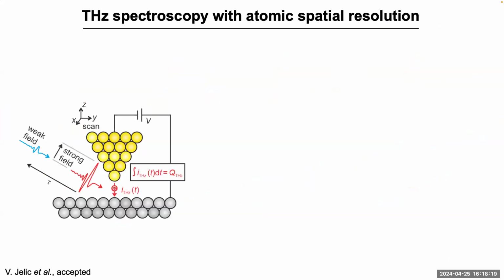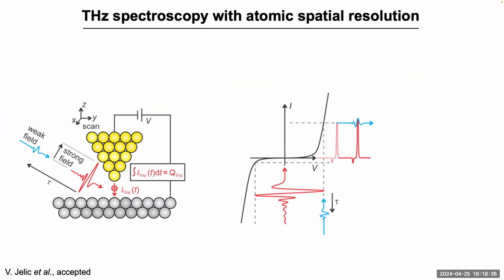It turns out you can do this pretty simply, actually. You just need a couple of beam splitters. What we do in this case is we have one terahertz pulse, which is strong. It's the one I'm usually talking about. And then one little baby terahertz pulse that's quite weak, and it might only be a few percent of the other one. We apply this terahertz field to some IV curve, and we generate some current pulse. We need to engineer this configuration such that we get a unipolar single-cycle current pulse.